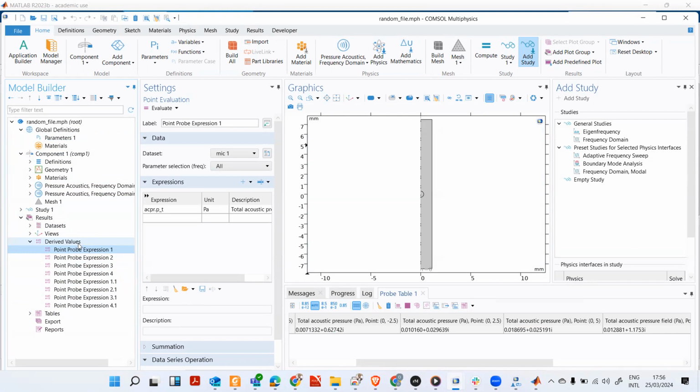With this optimization, I can have hundreds of different sets of parameters for the size of each individual Helmholtz resonator. I want to find what is the best combination of all of these sizes to give me the acoustic property I want. So I put everything into a MATLAB optimization tool, set this simulation as my function, and use it as a normal function to find the minimum value, minimum cost, and then it can do the optimization for me directly.